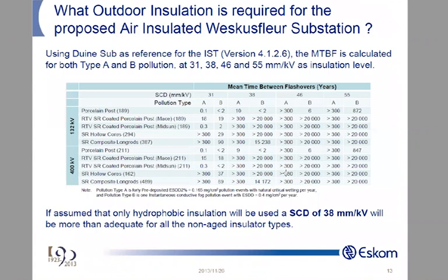So now what happens is their little CH3 hairs say, we don't want to show towards the pollution, this polar thing here, and the oxygens are drawn out, okay, and they pulled out of the material and they migrate. Low molecular weight silicones. Low molecular weight is there's very little molecules there, so it's a small little chain. It's a low molecular weight chain, and this little chain is this little thing that is now migrating out. And this polar thing here is attracting it, and these oxygens here are attracting to the polar.